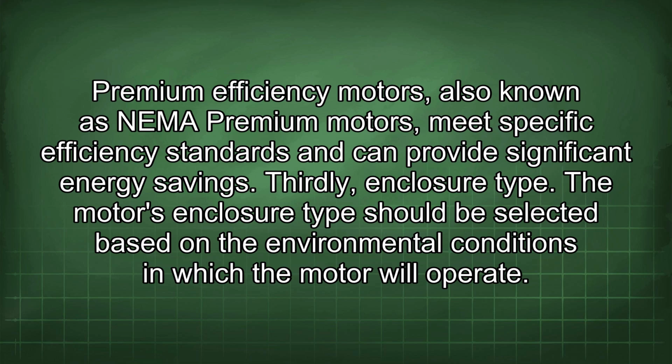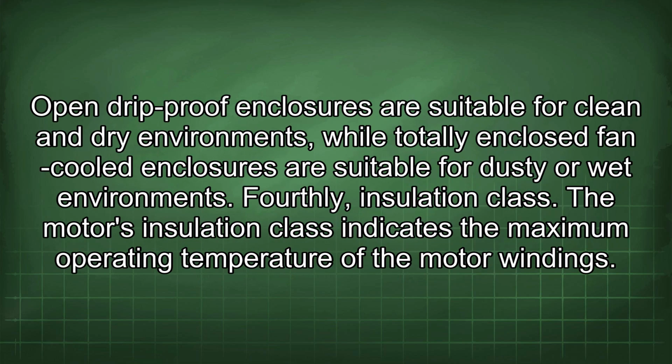Thirdly, enclosure type. The motor's enclosure type should be selected based on the environmental conditions in which the motor will operate. Open drip-proof enclosures are suitable for clean and dry environments, while totally enclosed fan-cooled enclosures are suitable for dusty or wet environments.